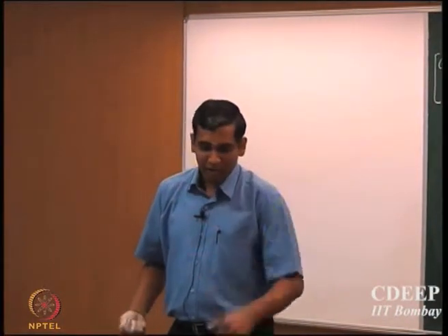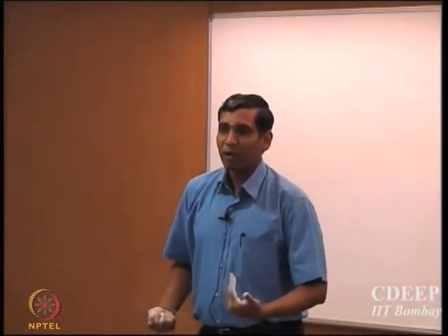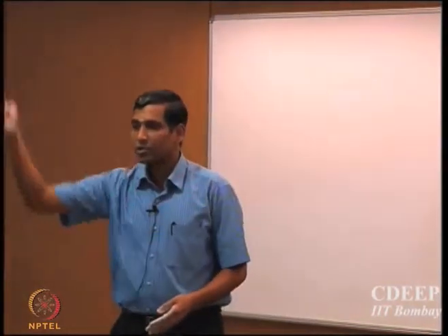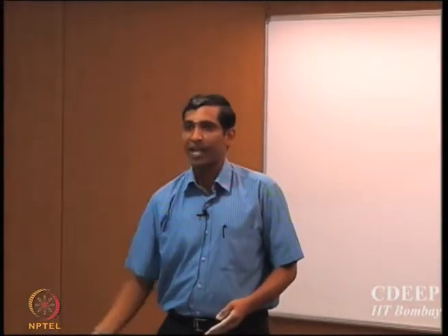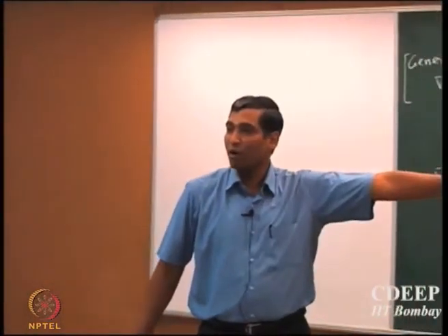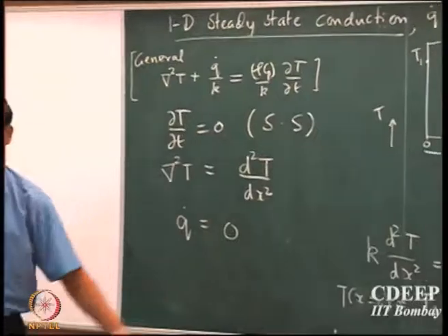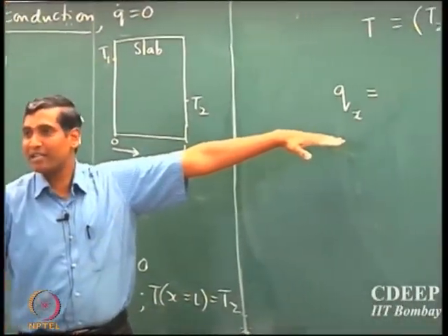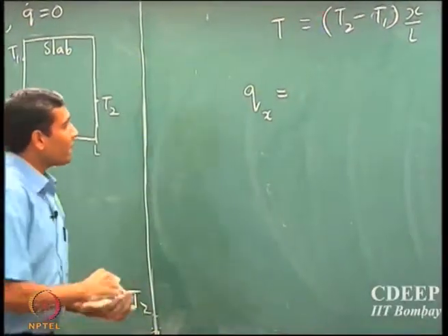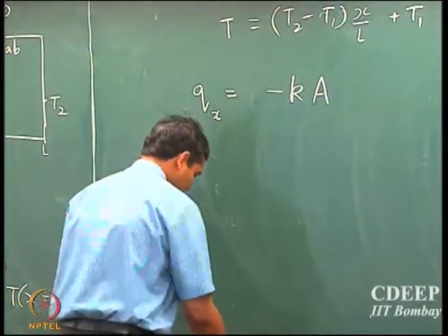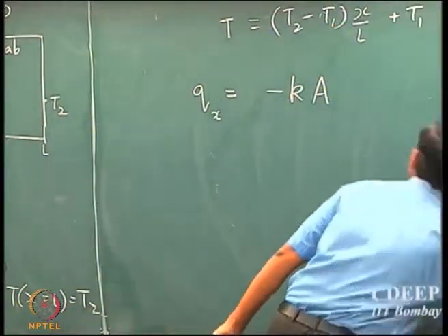When you look at a certain system, what somebody wants to know is how much heat is being transported, what is the amount of heat the system would generate at one wall or one end, and what is the amount of heat I am supposed to take from that end of the wall. Finding the temperature distribution leads towards finding the heat transfer rate, and the way to find it is very simple. We know that it is minus K, area of heat transport, multiplied by the corresponding gradient.